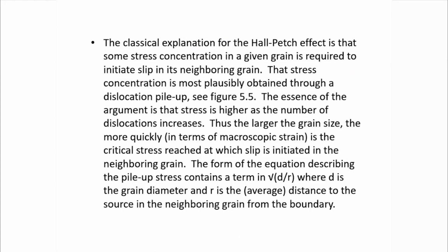The essence of the argument is that stress is higher as the number of dislocations increases. Thus, the larger the grain size, the more quickly the critical stress is reached after the slip is initiated in the neighboring grain. That is obvious, correct. The equations describing the pileup contain a term root d by r, where d is the grain diameter and r is the distance from the boundary to the source in the neighboring grain. Okay, fine, forget about r, but the pileup stress is basically proportional to root d, that is very clear, right.